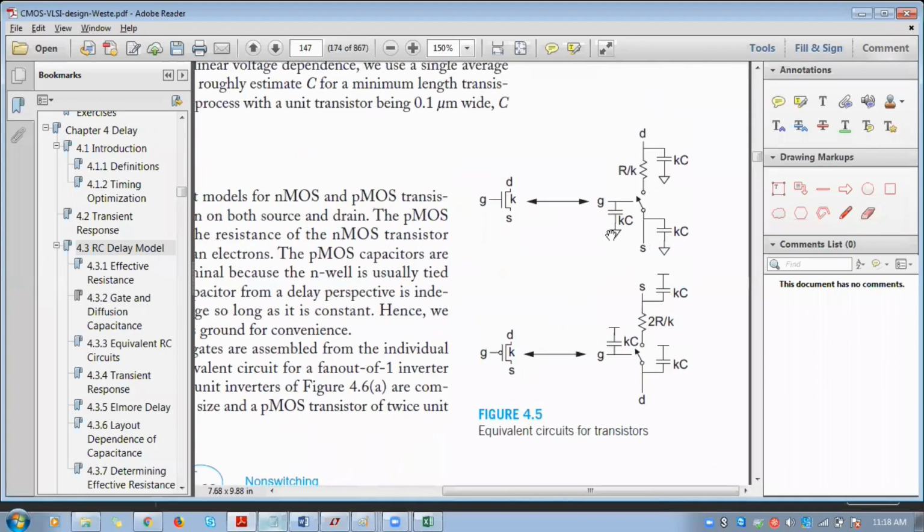We are seeing this capacitance effect and all, right? Actually, these capacitance effects are not physically present. We have seen CV characteristics, right? For every transistor, you have some diffusion capacitance, intrinsic capacitance and overlap capacitance, as you might have seen already. All these capacitance effects act as input as well as output capacitance. Physically, you don't have any capacitance in your transistor. These internal and external capacitance effects come from the CV characteristics we have seen already.